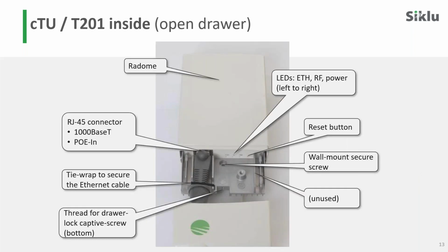And we can see here on this slide, basically now the doorway is open so that we can look at what is available inside the doorway. You have obviously an RJ45 connector, which connects the data and power into the unit. The cable that must be used is a shielded RJ45, obviously UV resistant, and the connector at the end of the cable must also be a metallic RJ45 connector, so that the grounding provided by the shield of the RJ45 reaches all the way into the unit.